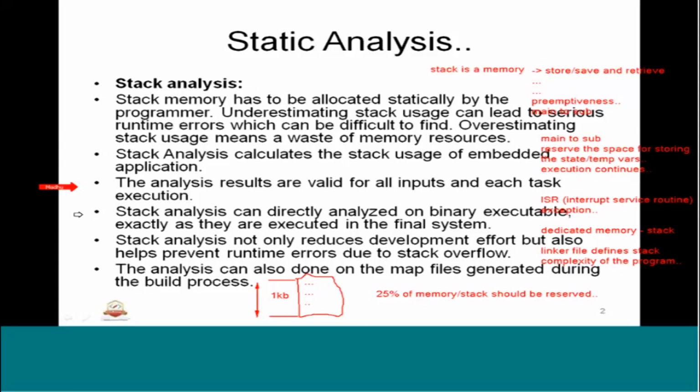So basically, stack analysis calculates the stack usage of the embedded application. Stack analysis can directly analyze the binary executable. Yes, we know, because the binary executable is the one which will be running throughout the embedded software execution, exactly as it is executed in the final system. Stack analysis not only reduces development effort but also helps to prevent runtime errors due to stack overflow.